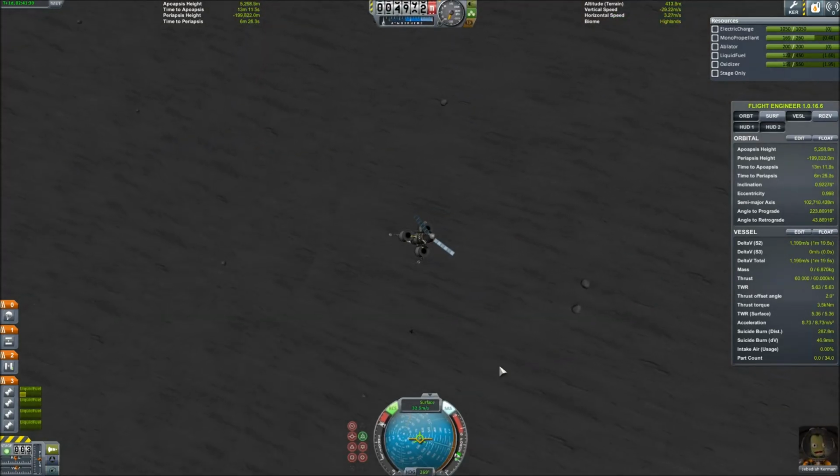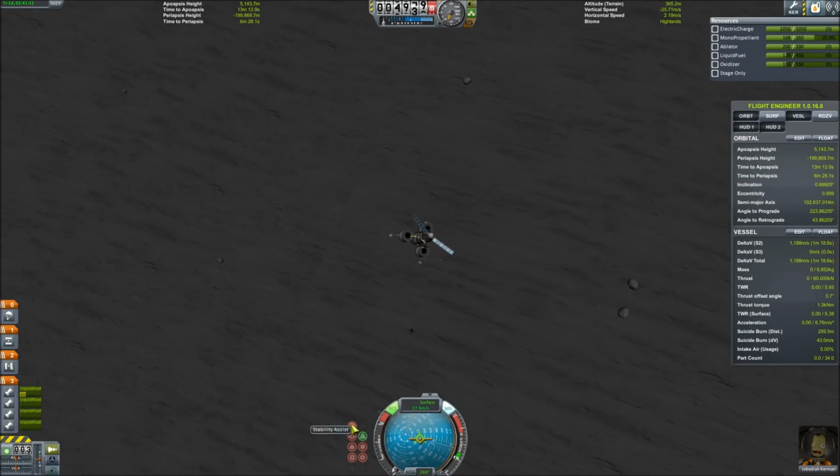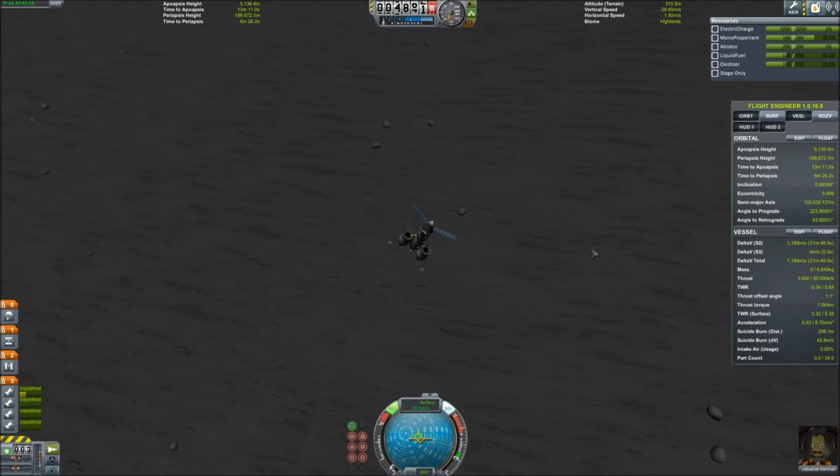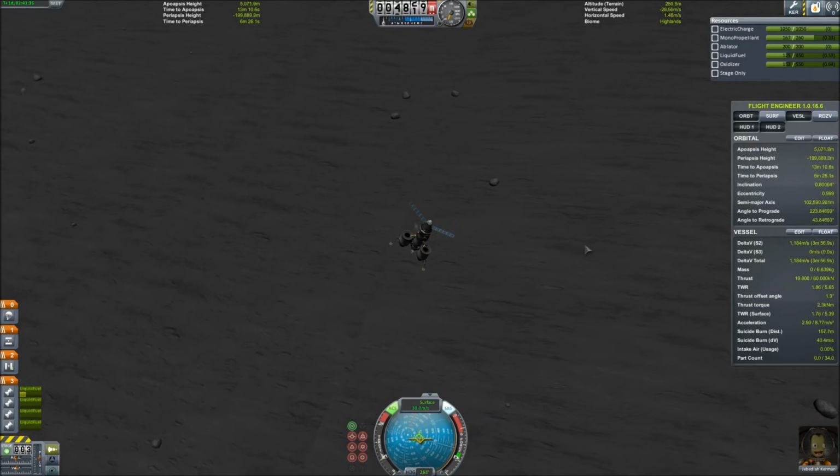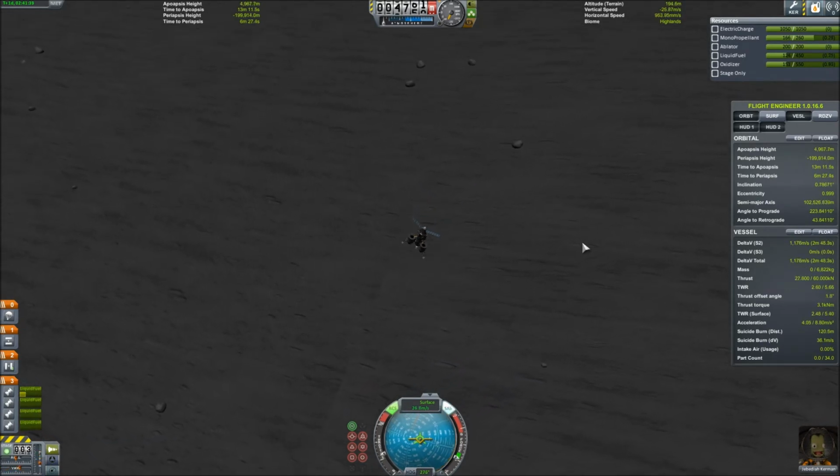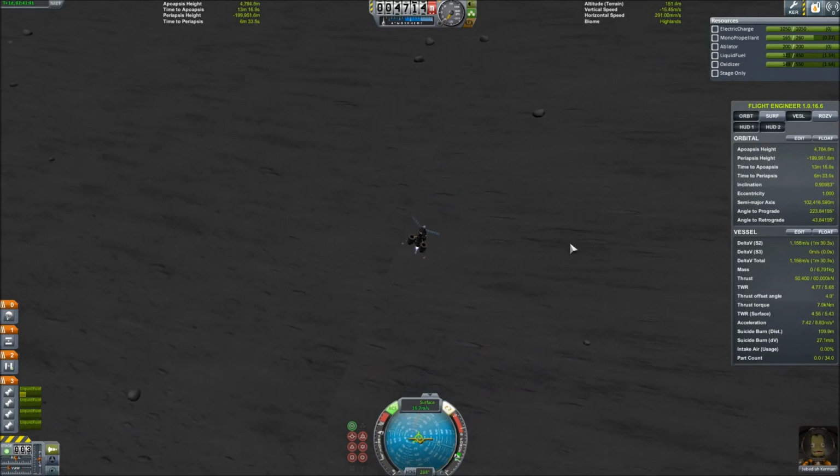As you continue to lower yourself down, continue decelerating by using the throttle. Whenever your landing legs actually touch the ground, you want to make sure that you're traveling less than 5 meters per second, or you'll risk breaking them.